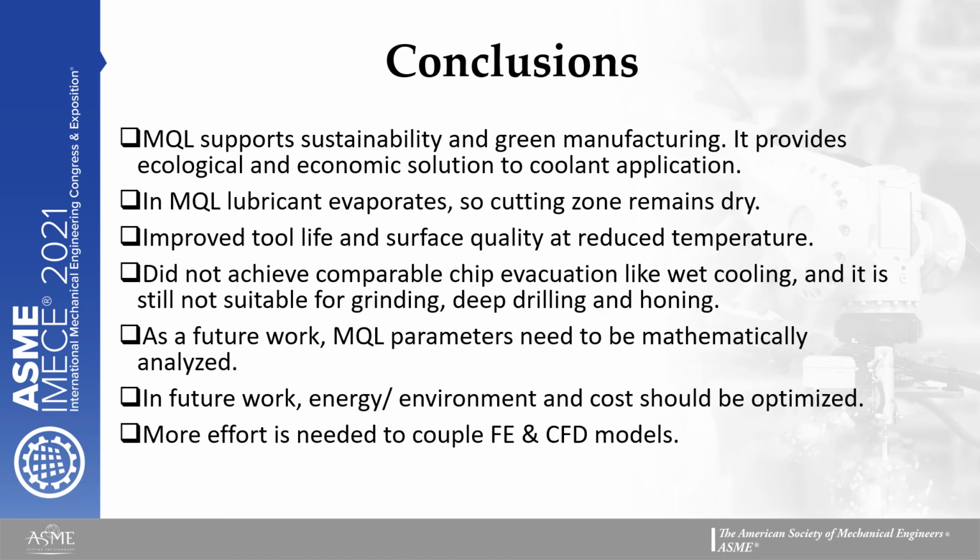The major conclusions of this study are as below. MQL supports sustainability and green manufacturing. It provides an ecological and economic solution to coolant application, and it has the potential to replace conventional flood cooling. In MQL, the lubricant evaporates, so the cutting zone remains dry, which is again an advantage over the flood cooling method. Improved tool life and surface quality at reduced temperature.